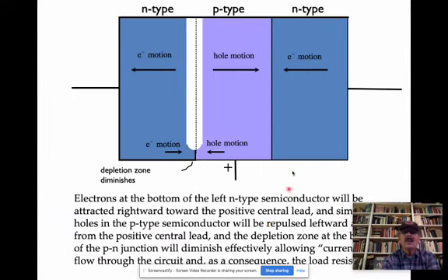And the cleverness is wrapped up in how you treat this terminal, the terminal that's attached to the central material. Because if you make this terminal electrically positive, and I might add, this device is called a transistor. And there are two different kinds of transistors. There are NPN transistors, and then there's the other version where this is P, this is N, and this is P. So they're NPNs and they're PNPs. We're dealing right now with an NPN transistor.